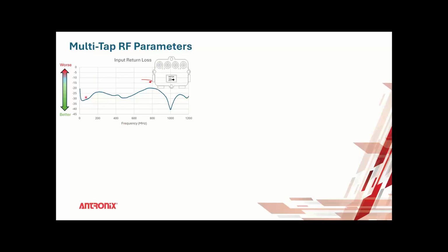Return loss. So return loss is what we mentioned before. Some of the signal level coming in is reflected. I mentioned before 20 dB return loss. Here about 99% of the signal level is transmitted. Return loss is not continuous with frequency as well. Each frequency has a different return loss, and specifications are usually worst case return loss. So this would be a typical plot out to 1.2, and the higher number here is better for return loss.